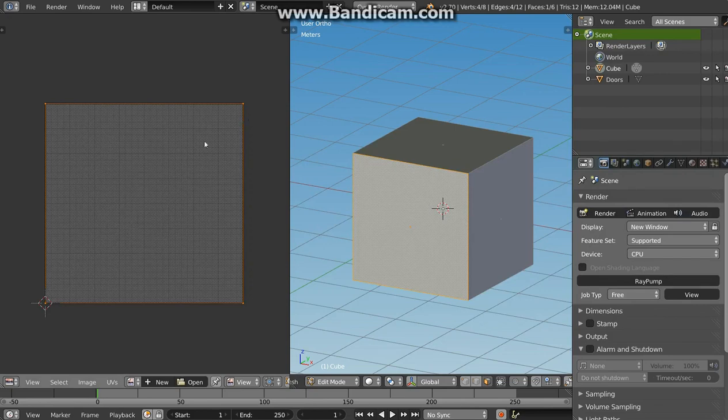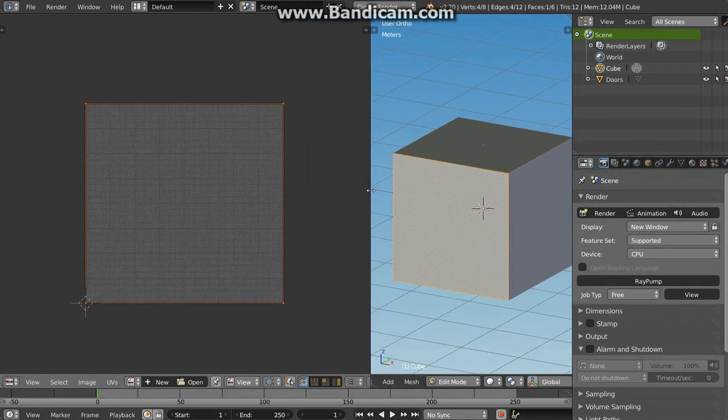and you can apply all the same operations as if you were modeling. You just model only in the 2D space, so you can scale the face, you can rotate, you can grab it, and you can even work with vertices. I just place the 3D cursor, the 2D cursor, and model as you would work with a simple plane.